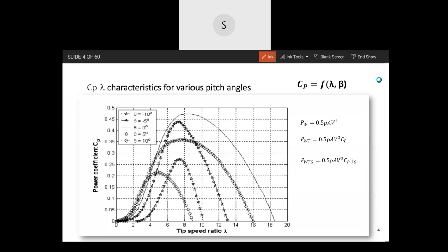It is changed on both sides of the default design value, 5 or 10 degrees on either side, and both cases, as you are seeing in the graph, all the values come down. So the usual design pitch angle beta is around 5 to 7 degrees.